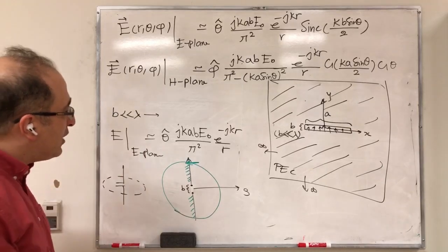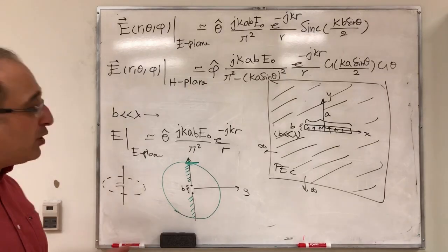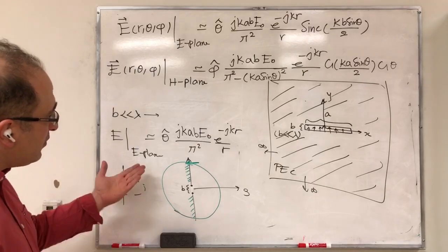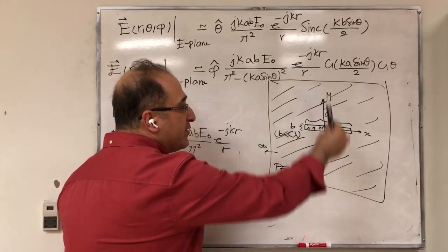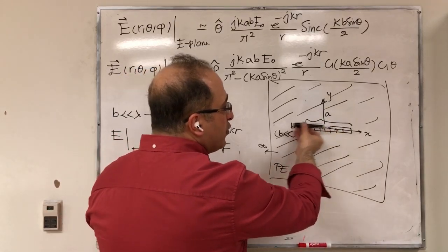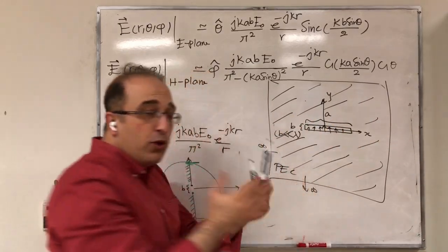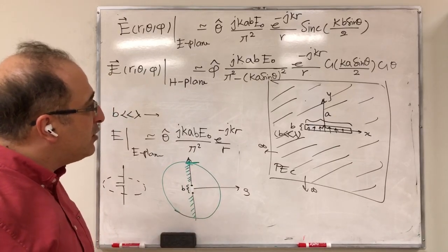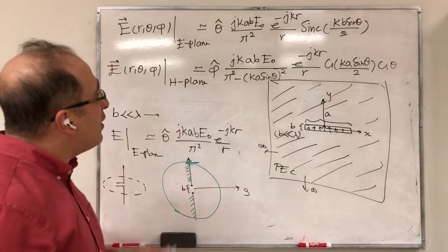This happens in the E plane of this, but for the dipole, it happened in the H plane, and also the polarization was different. The polarization of this right now is vertical. If you look at that, this is the way that it radiates. If you have your complementary dipole, the dipole would be in this direction, and the electric field becomes horizontal. So the polarization also changes. So when you have the complementary structure, you need to be aware of these things. So now let's go and check the H plane.